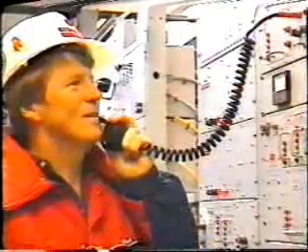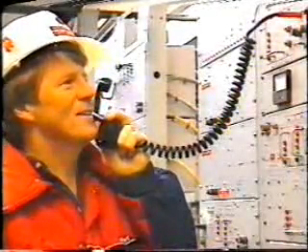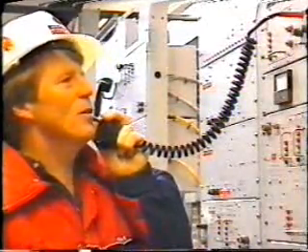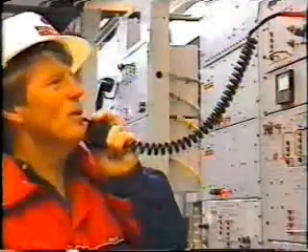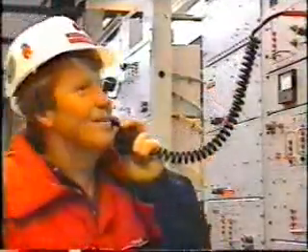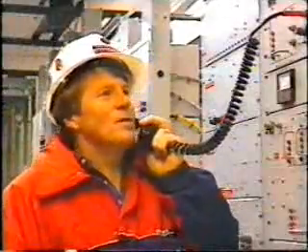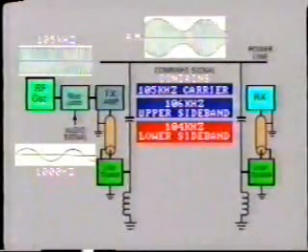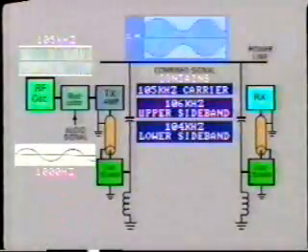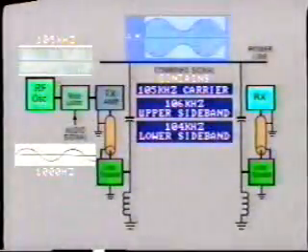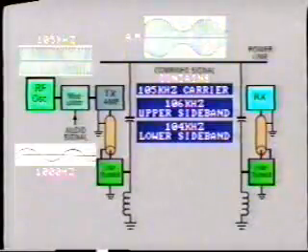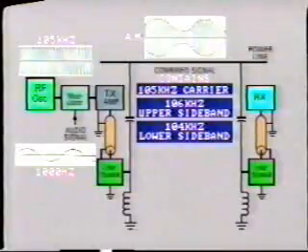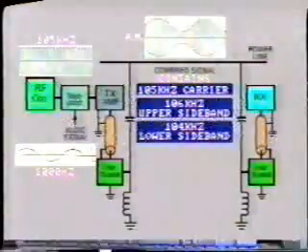With voice modulation, these upper and lower frequencies will be changing all the time within, say, 3 kilohertz up or 3 kilohertz down from the carrier frequency. The lower sideband is actually a mirror image of the upper band, just like the modulated signal envelope that we looked at. But only one of the sidebands is actually used after demodulation. So why do we need to transmit both upper and lower bands?